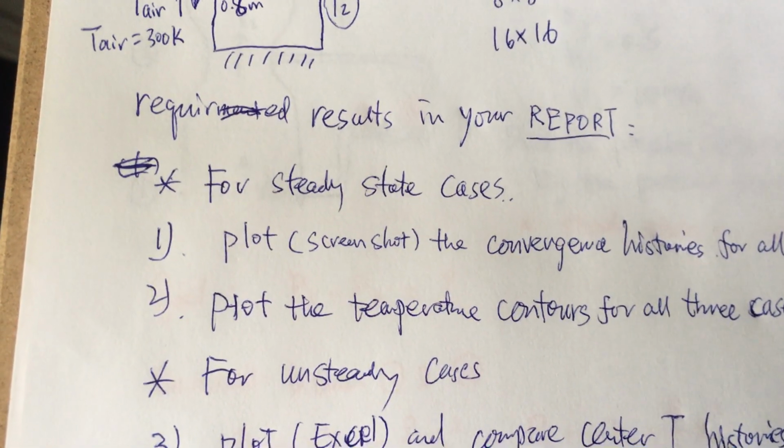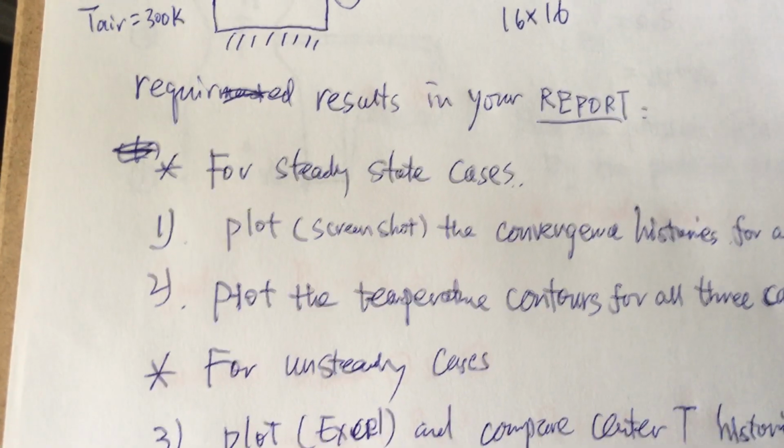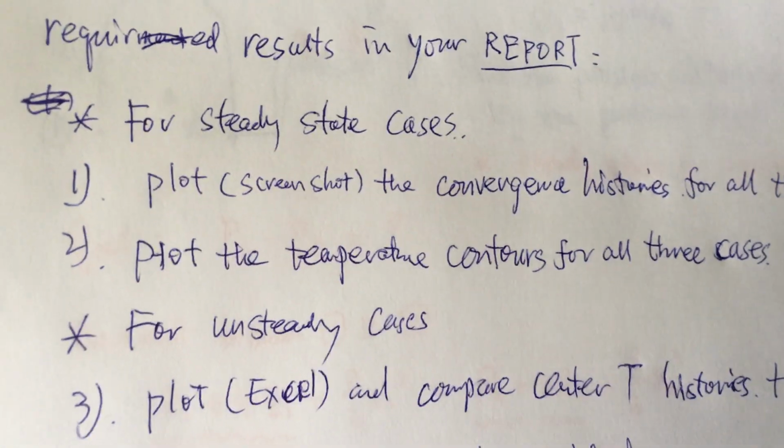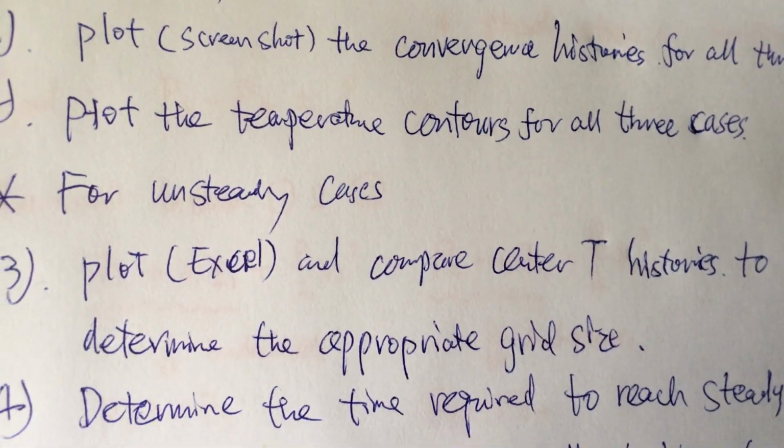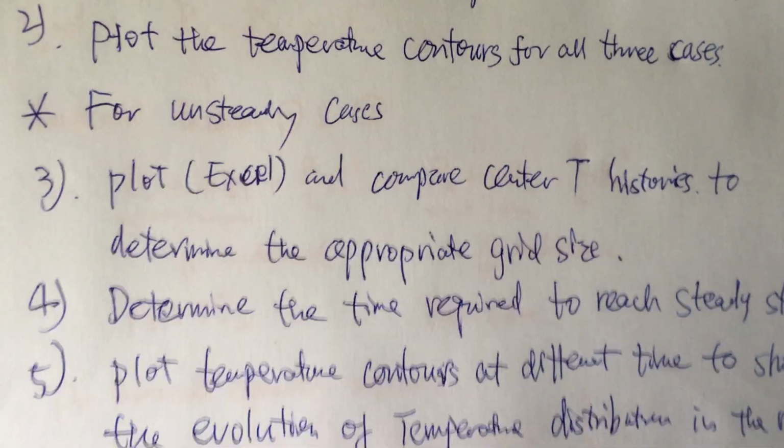So there's no need to further refine. That's the logic we want to see, okay? We want to prove. So this is number 3. I want you to plot the 3 curves in one plot and compare to decide the grid size.